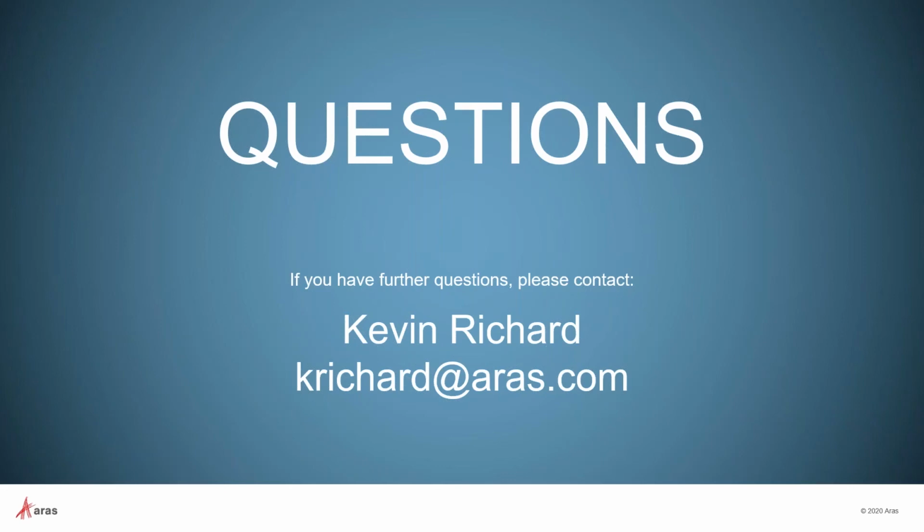Second question, can I use query parameters to select parts to display? So actually, you could do one of two things. I showed view modes today as a way of using the rendering attributes of color and transparency to highlight, or in some cases to de-emphasize components. So you could create your own view modes that are triggered based on some parameter that you define, or you could use parameters to affect the conditional logic in the query, so that when you re-execute the query, you are filtering all but those which you want to see. So there's two ways of doing that.